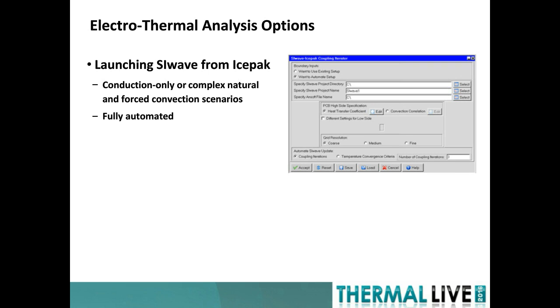So we have another interesting question. This relates to the flow between the three simulation tools. The question is, can we import the ECAD data directly into ANSYS Mechanical? Yes. That's a supported feature since 17.0. So you can import the ECAD into ANSYS Mechanical in the same way that you do for ice pack.